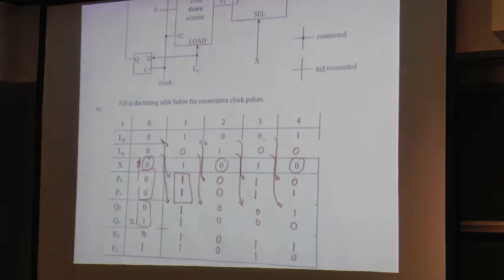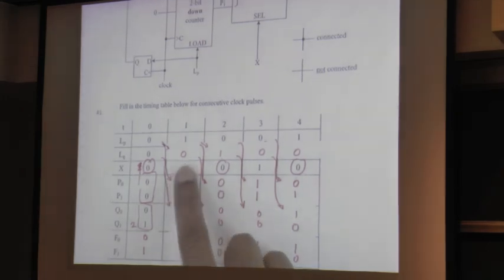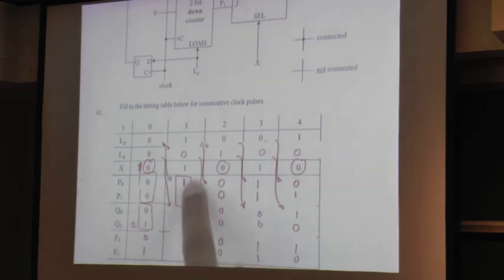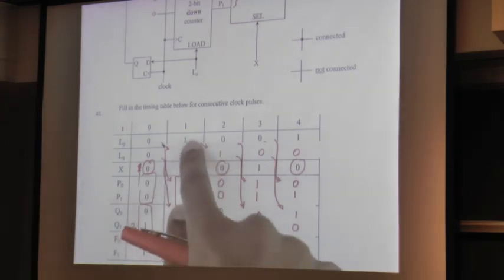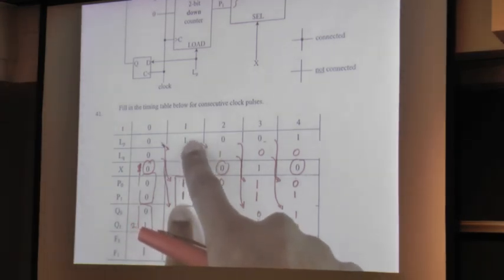This is basically because time goes forward. The past can only affect the future. So remember, everything in a circuit with a clock, all useful sequential circuits have clocks, and things only change at the clock's rising edge. So every decision is made at that instant. At that very instant, this decision here is being made, this P0, P1. But this value of LP right here does not exist at that instant. That hasn't happened yet.